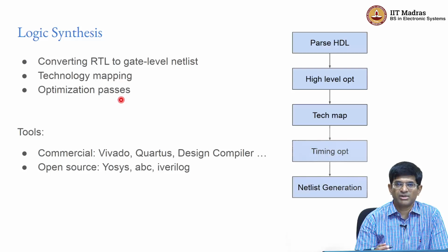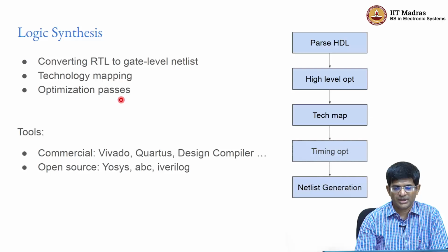So, are there ways by which we can find blocks of code that are redundant or can be eliminated or can be pre-computed while you are actually performing the compilation step itself, right? And not just that, after you have gone into some kind of an intermediate representation, what are the other kinds of optimizations that we can do? Things like Boolean optimization, FSM state optimization, all of those fall in this category, right?